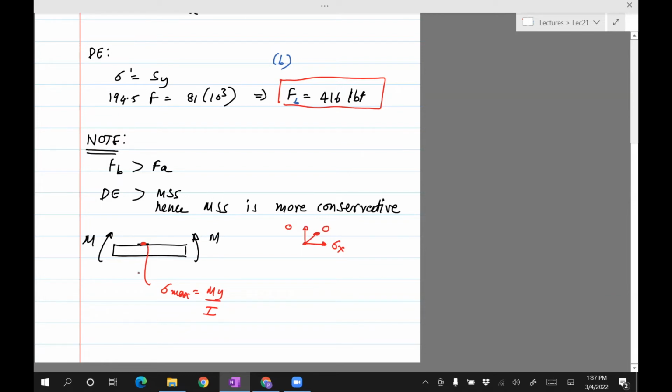So we just have to pretty much do that. In this case, we can think of this as the rod subject to M. And then since it's anchored, it's also going to have a moment the other way, which is going to resist bending. So this looks very similar to this one in this plane, right? The top part will have a stress in this direction, sigma x. Similarly, this will have a stress in this direction. And the other stresses are all zero.